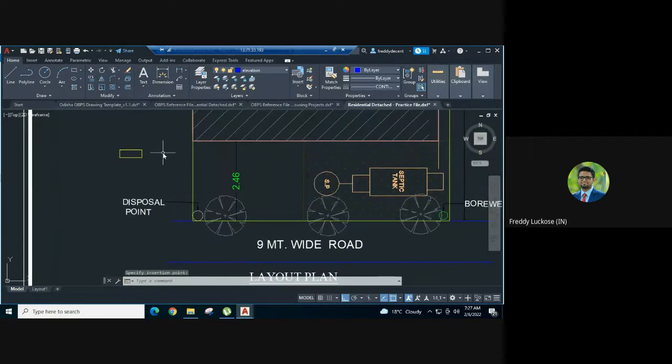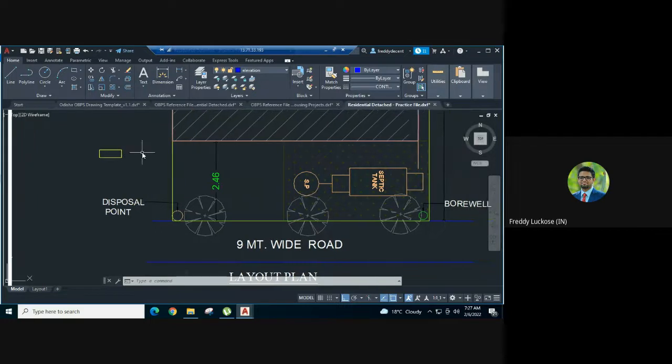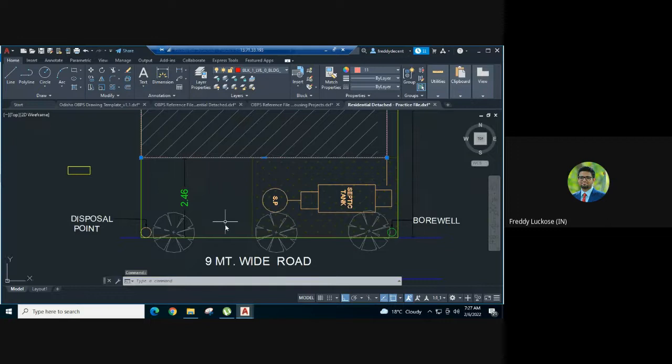Then we can create the polygon for front setback. Now the way to make the setback polygon is, you have to make a polygon which has all its edges either falling on the building footprint or the plot boundary. There shouldn't be any edge points of the setback polygon that are not falling on either of these components. It shouldn't be lying anywhere else. All the points should be either falling on building footprint or the plot boundary. I'll just showcase how to make it.